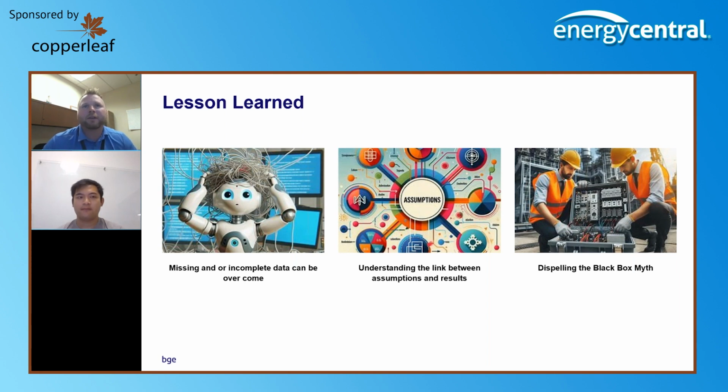Other things: we go through and say which assets, if they were to fail, would cause an outage. Arresters cause outages and circuit breakers cause outages. We ran the analysis with a constraint and it said, an arrester is not very expensive to replace and a circuit breaker is very expensive to replace, so you should just replace a lot of arresters.